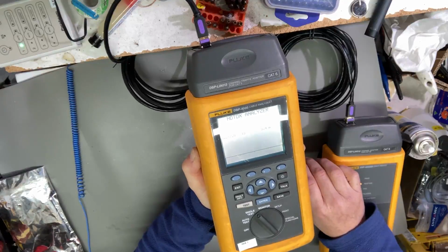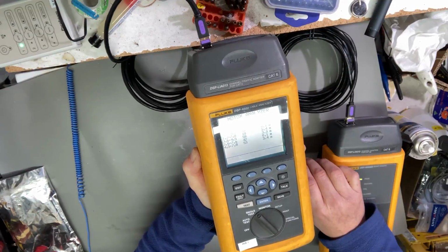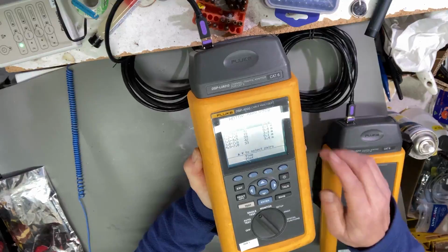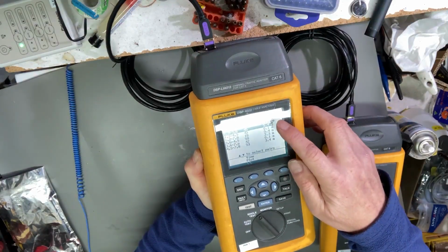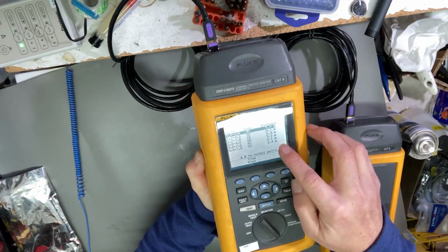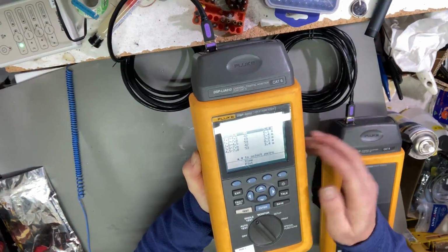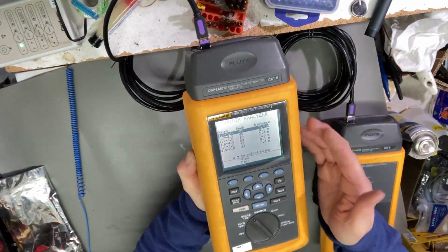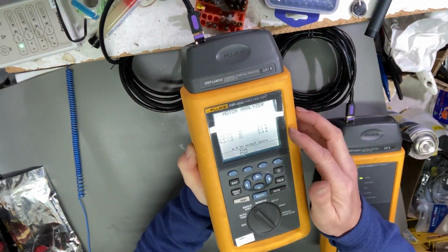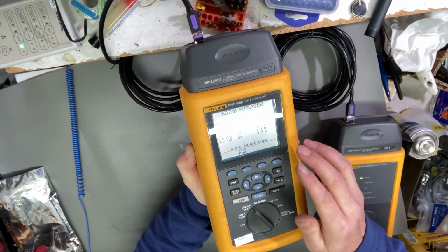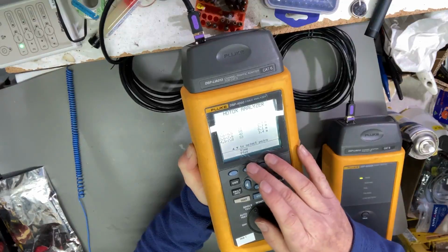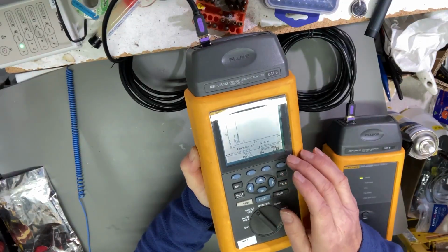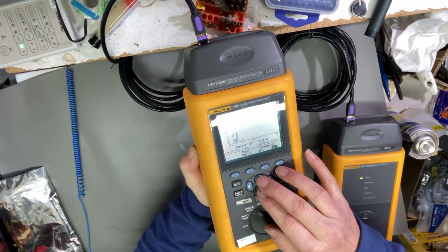Let's have a look. Notice too that it's giving the peak result and the distance to that peak. So basically where the worst bit of the cable is, which is right in there. So 3 plus 1 will be 4, it's saying actually 4 meters. It's actually saying 5.4 there, 3.3, 5.4. It's somewhere in the middle of the cable there. It's going to go view plot, but this time I'm going to adjust scale here.